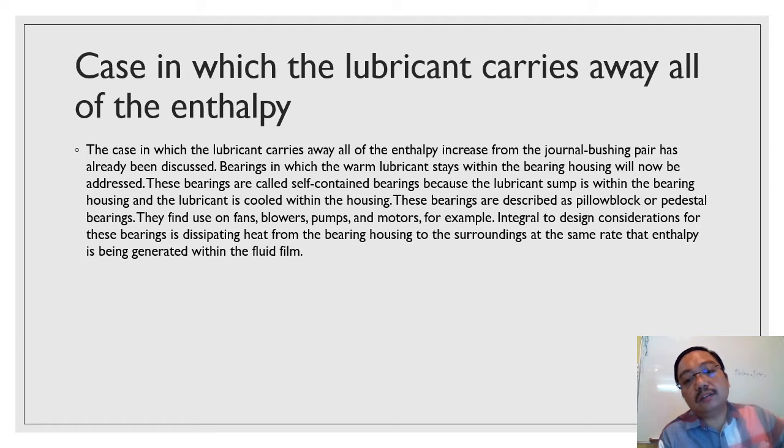This bearing is called a self-contained bearing because the lubricant sump is within the bearing housing and the lubricant is cooled within the housing. These bearings are described as pillow block or pedestal bearings. They find use on fans, blowers, pumps, and motors. Integral to the design consideration for this bearing is dissipating heat from the bearing housing to the surroundings at the same rate as enthalpy is being generated within the fluid film.